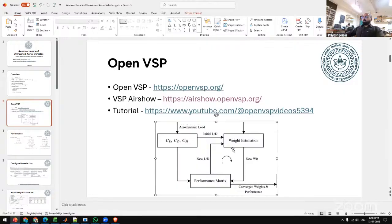Next is why we are doing this CFD analysis. Once we get our CFD loads, how will we use them? We have CL, CD, CM with us. With this, we will have some initial L by D for the model. We have some initial weight estimation. With that initial weight estimation, we'll do the performance calculation. I will tell you what the performance calculation is; they have to converge. Let's say the initial weight came out to be 10 kgs or 20 kgs, let's say 20 kgs.